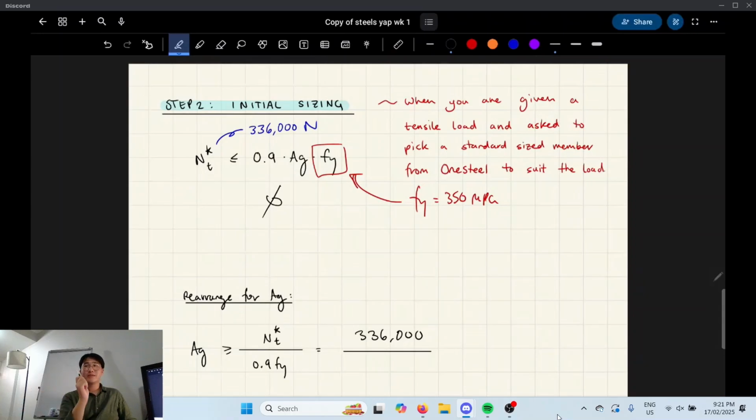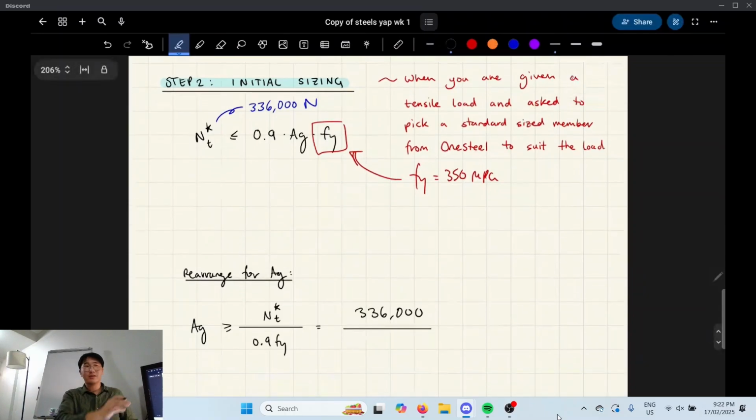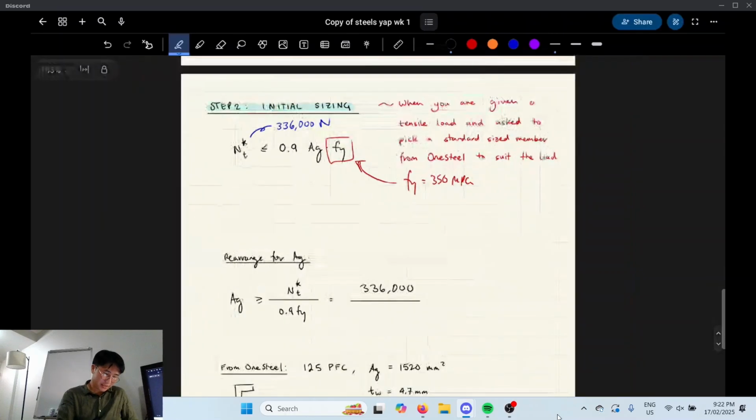Buckling is a thing that really messes up compression members for steel, so it's essentially weaker. Most of our steel members are going to have some kind of buckling involved, because it's a small cross section for how long it's going to span. So for compression, this might be something like 0.5 as an initial guess, but it really depends on the structure and how long the member is. Tension's quite simple because there's no buckling to consider. I'm getting ahead of myself. We'll talk about that next week.